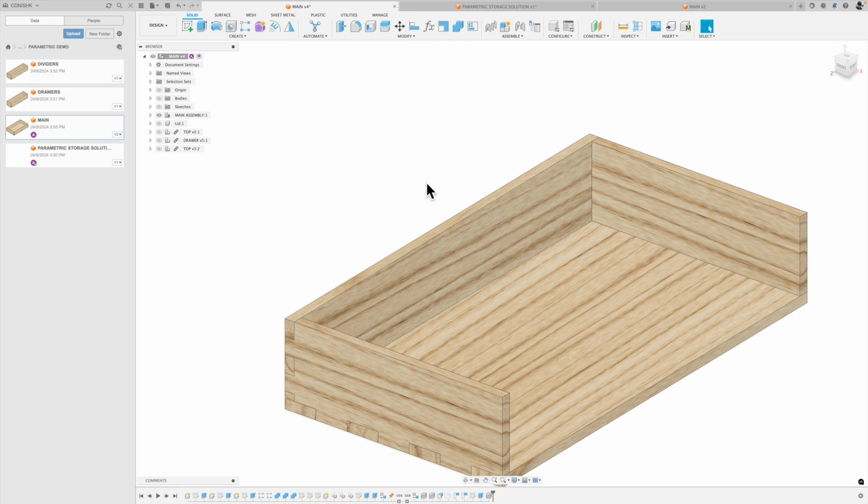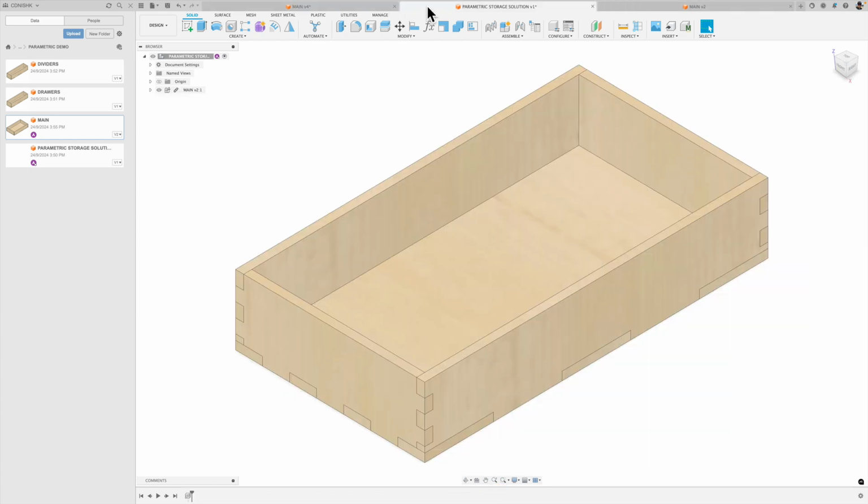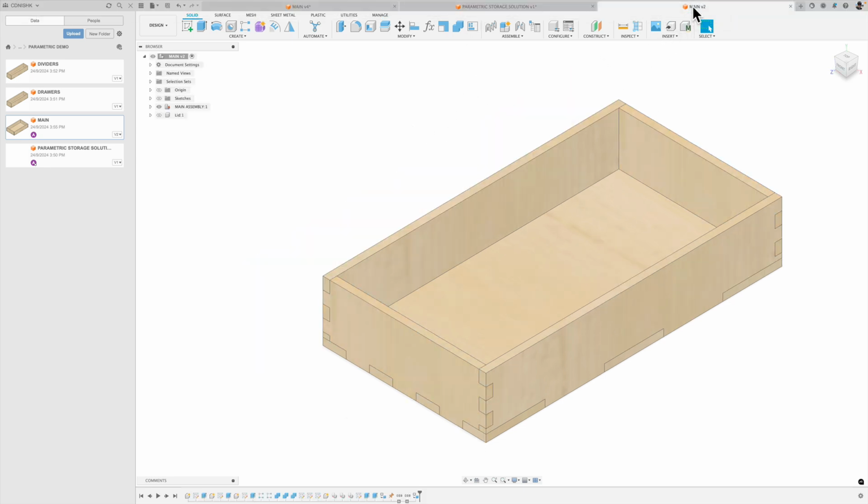So now we're going to remove one of the bodies of the parametric design to make it match our intended design. One of these walls I'm going to remove, so we'll go ahead and make sure we select it, and we can see from the browser when we select it on the model which is the one we want to manipulate.